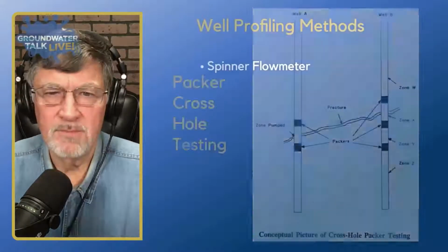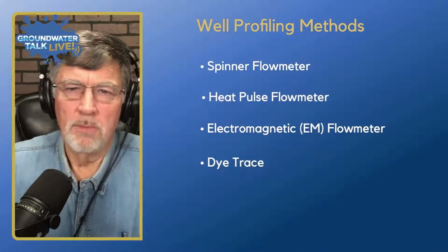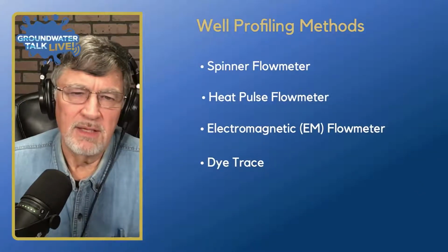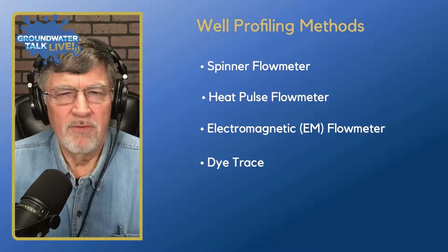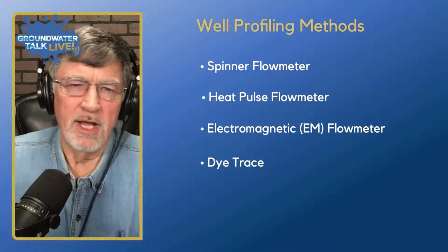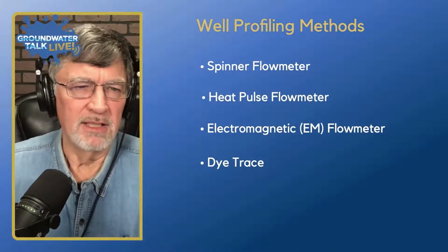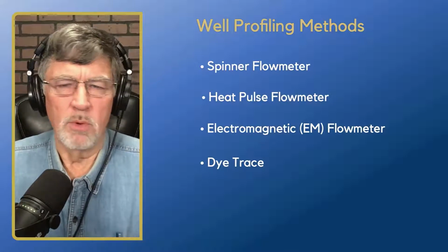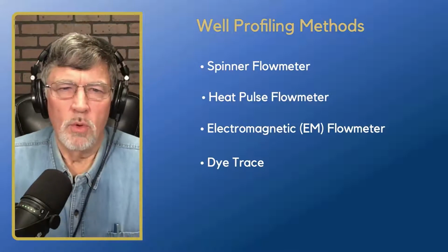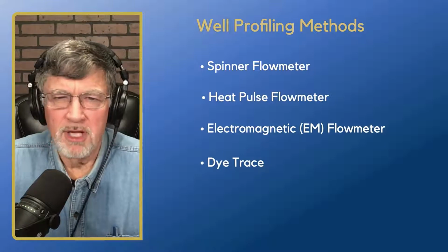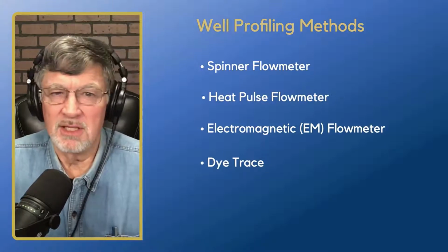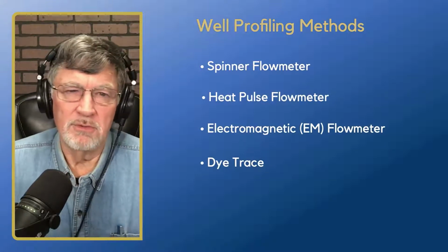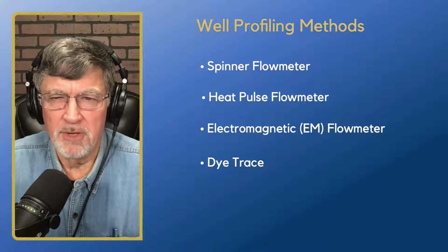All right. So well profiling methods. We're going to get on to well profiling, and there's really a number of ways to do well profiling, and that's what we're looking at here. So first of all, we have a spinner flow meter, and I'll look at each of these in turn. I'm just doing the list here. A heat pulse flow meter.